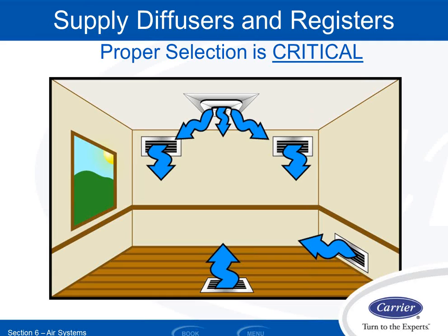Residentially, what you're going to find is the vast majority of systems are going to have their supply and returns at the floor level. That's going to be the most common for two reasons. One, in residential, I'm mostly in the heating mode, so I typically want to supply that heat from the floor level where the occupants are. But two, a lot of systems are basement located, so the ductwork is shortest if I do my supply and returns from the floor level.